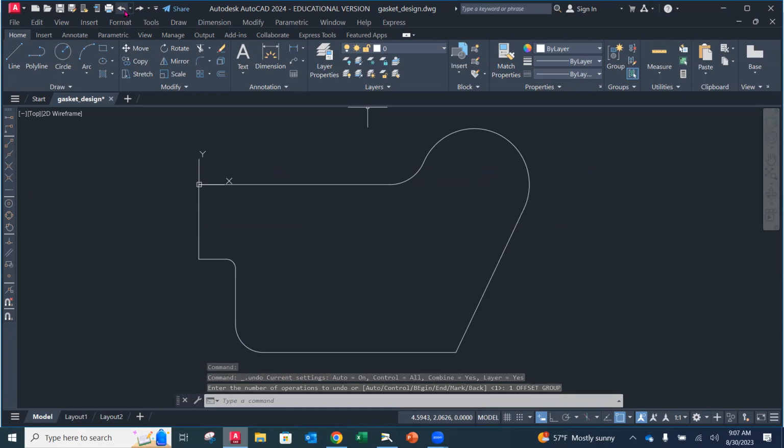Polyline command. We are going to take this entire perimeter on the outside. We're going to make it one entity. Notice how right now when I select, this is a separate line, this is a separate line, separate radius, they're all separate. And so when I did the offsets, it was only looking at that one entity and offsetting it, okay, and duplicating what was there.